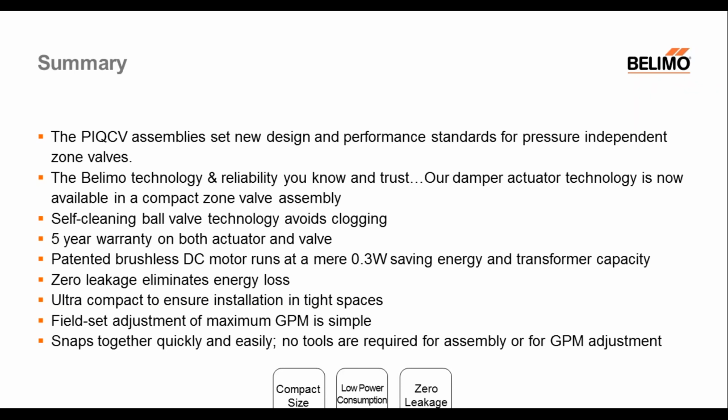That you're saving energy by using an actuator with very low power consumption, or you can buy a transformer of a smaller size, so less than a 40 VA transformer. Or if you had a 40 VA transformer, you can wire more actuators to a single transformer without having a concern of not enough power.